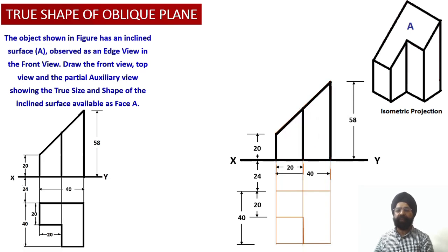Now let us complete the front view projections as darkened ones as they are appearing to an observer. So this is the front view projection as they were provided to us. Next, we need to complete the top view projections of the solid so that we are able to see that the section surface appears as an edge view in the front view, and as a foreshortened view, or a reduced view, or the apparent shape view in the top view projections onto the horizontal plane.